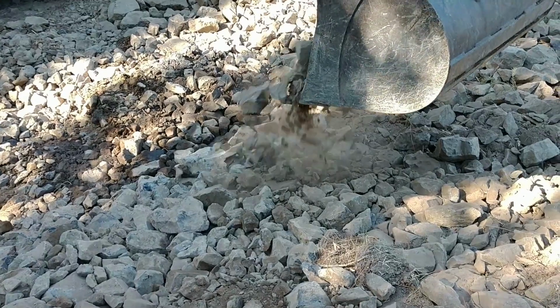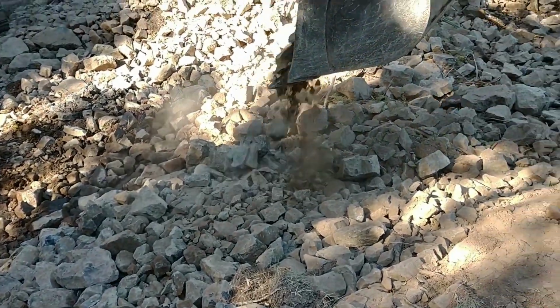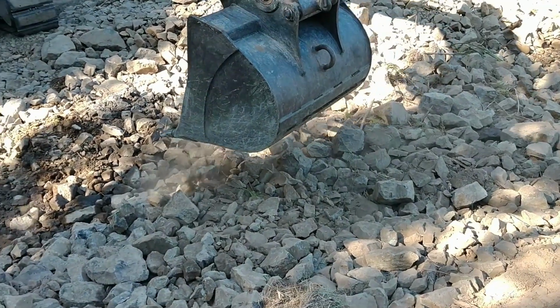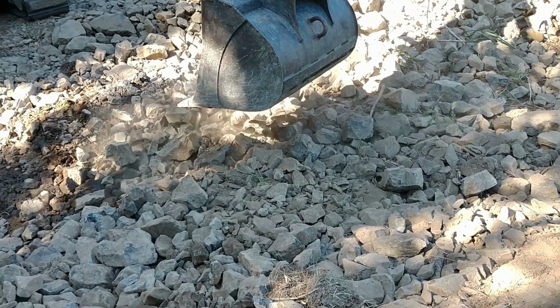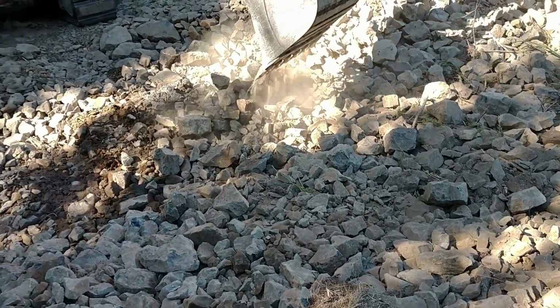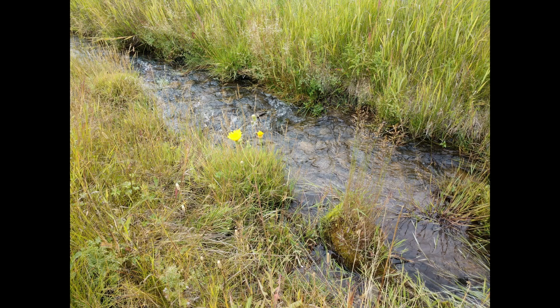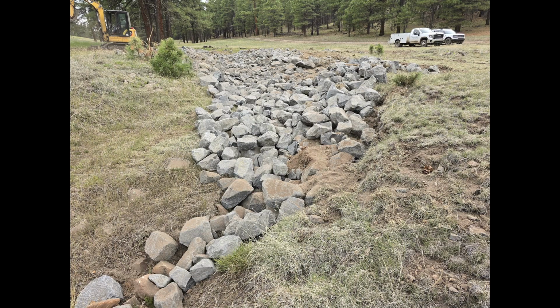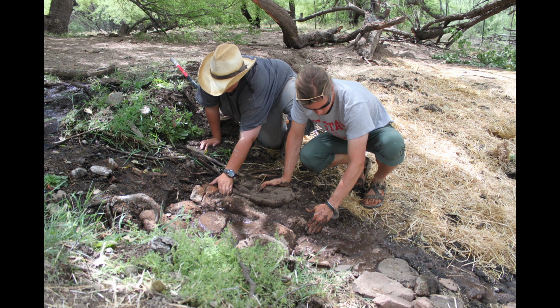The rock should be spread in a layer that is at least 12 inches thick. Make sure to armor the entire width of the floodplain and extend the rock up on the banks of the spillway so there will be no erosion during a flood. The rock must be embedded into the ground so that water does not flow under or around the rock. The rock armoring must be done along the entire length of the spillway. Act to immediately repair a spillway by hand whenever possible to control erosion.